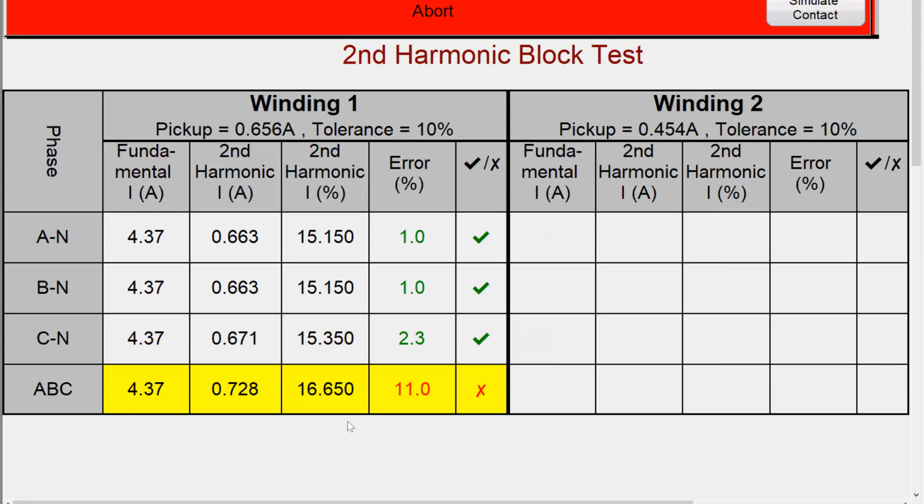So here I have the three-phase test that is going on, and it's the same kind of calculation. Now it's going to inject 3 currents on all the phases at 60 hertz, and 3 more currents on the same phases at 120 hertz. So the SMRT units have the capability to inject more current waveforms utilizing just a single current channel. It can in fact inject up to 4 different frequency waveforms utilizing the same channel.